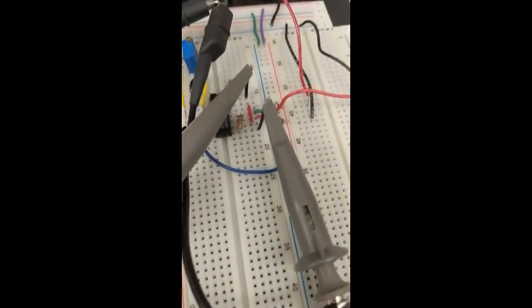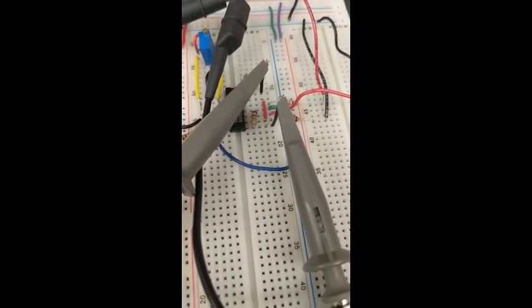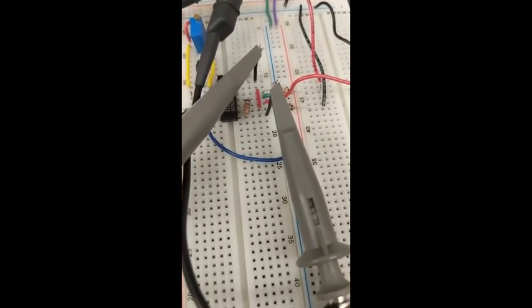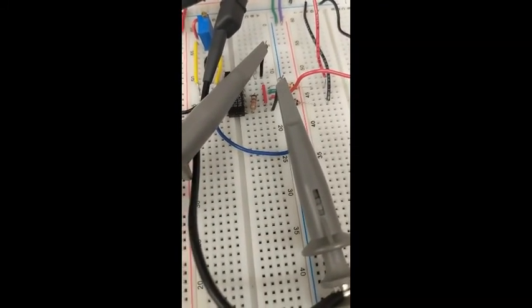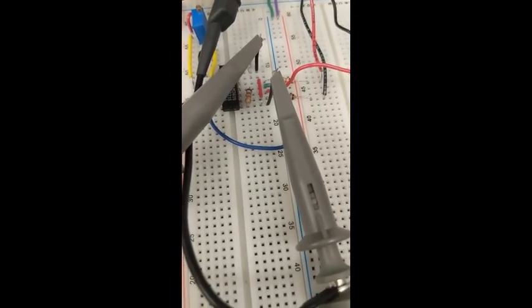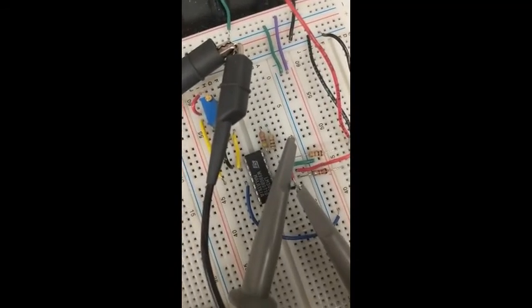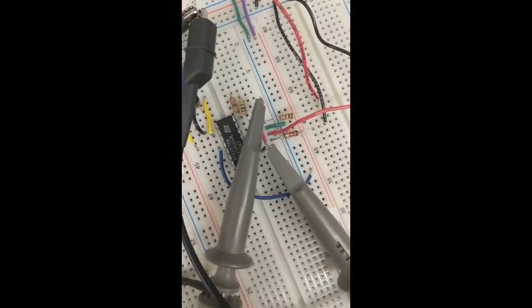This is our circuit for part B, and this is our input waveform. We input a 1 kilohertz triangle waveform of amplitude 2 volts offset 2, and this is because the Digilent can't supply voltages over 5 volts. So to correct that, we use the op-amp with the gain of 2.5 to create a 10 volt peak-to-peak positive triangular waveform.